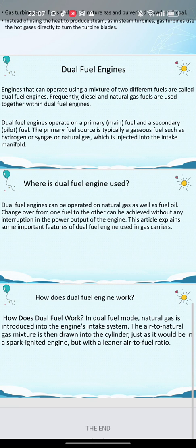So the disadvantages of steam turbine: relatively high overnight costs. Steam turbines are less efficient than reciprocating engines at part load operation. They have longer startup than gas turbines and even reciprocating engines. Less responsive to changes in power demand compared with gas turbines and reciprocating engines.